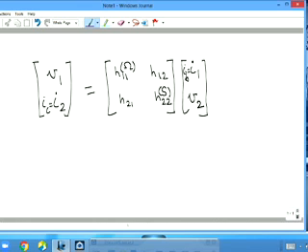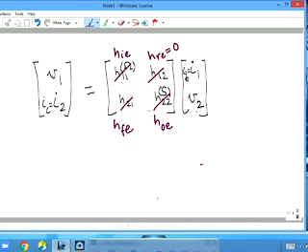Anyway, so we have not been studying BJTs at all. BJTs are where the hybrid parameters are used the most, and typically in a BJT, instead of calling it H11, you are going to call it HIE, and H12 is called HRE, which happens to be equal to 0 for a BJT, and H22 is called HOE, and H21 is called HFE. So these are the nomenclatures for the BJT, and that's that.